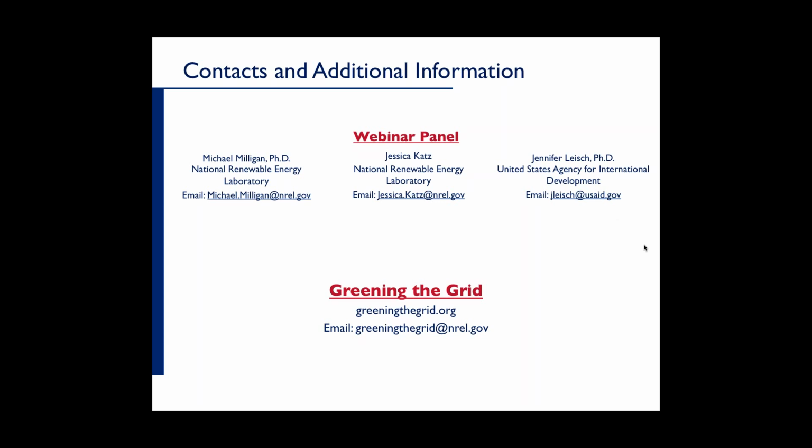And part of that process, when you have wind and solar, is to develop a day-ahead forecast. Now, the day-ahead forecast by its nature is not going to be as accurate as a forecast would be, let's say, 1 hour in advance. But the day-ahead forecast can typically provide enough information so that I can decide whether or not I want to start a particular thermal plant or not start it.